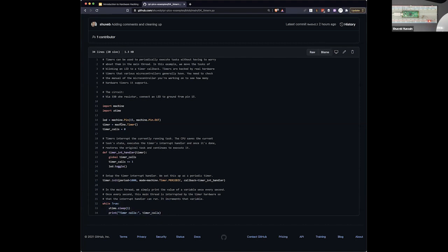And then what we are essentially doing is that we have a function, which is called an interrupt request handler. So we are setting up a timer here to go off every 1 second, right? This is in milliseconds. And this is a periodic timer. You can even set up timers for one shot. They'll fire and then it will never rearm the timer, okay? Here the timer is rearmed periodically, meaning that every 1 second the timer expires, this function gets called, and then the timer is rearmed so that it can get called again, right?